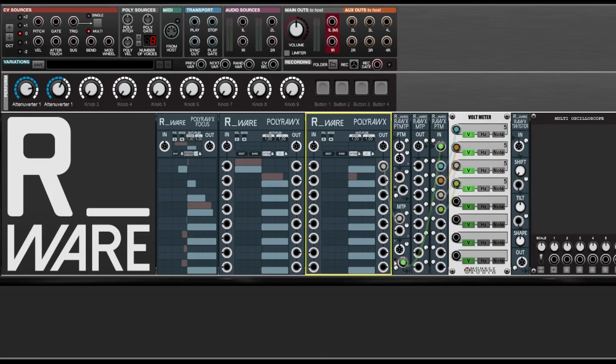Again, there's a little switch that lets you use the average of these channels. So we have 5 volts input voltage here at this monophonic jack. We have 8 channels of poly voices, and with the switch in the lower position, each polyphonic channel gets the full 5 volts, and with the switch in the upper position, each channel gets the input voltage divided by the number of poly channels.